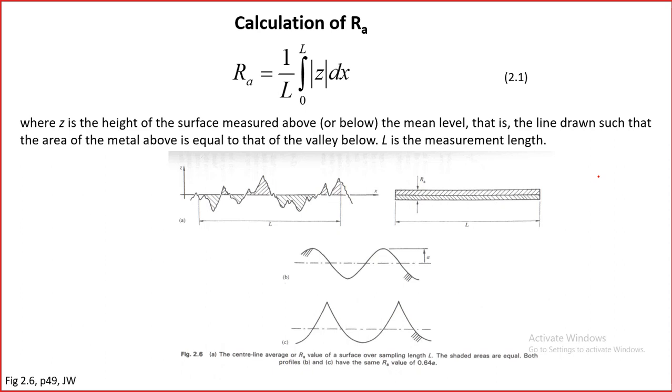So good morning again. We were talking about surface texture and surface roughnesses. One of the parameters that we often use, and a very popular number, is Ra. Ra is basically a number that we can get from the surface. For example, if the surface has got this roughness, and for all the data that we have, this is the mean line.